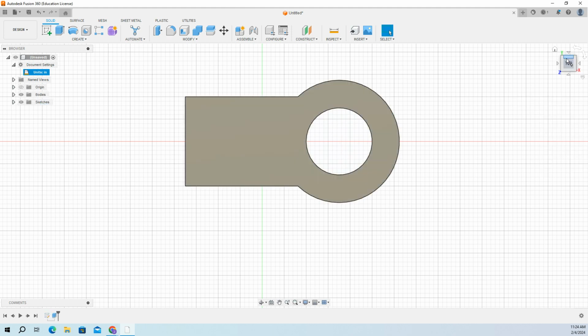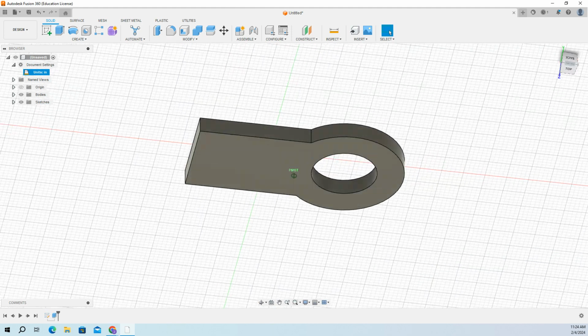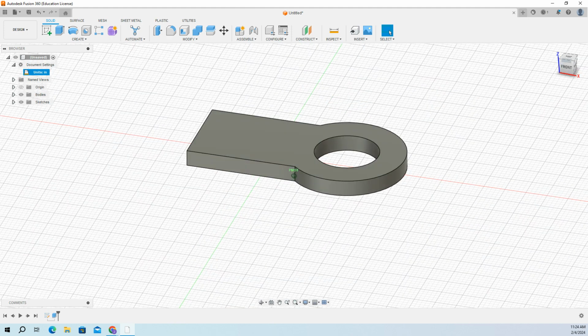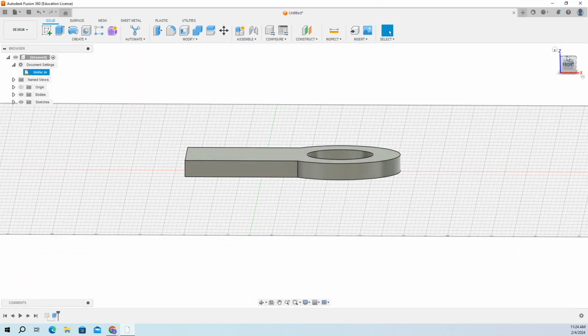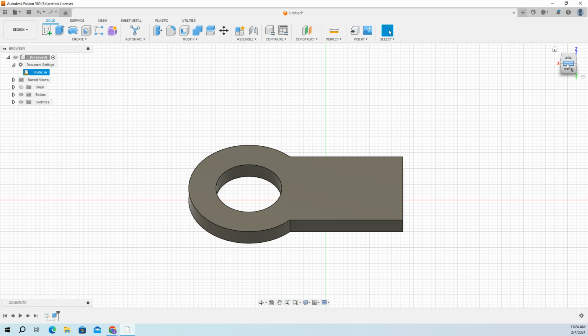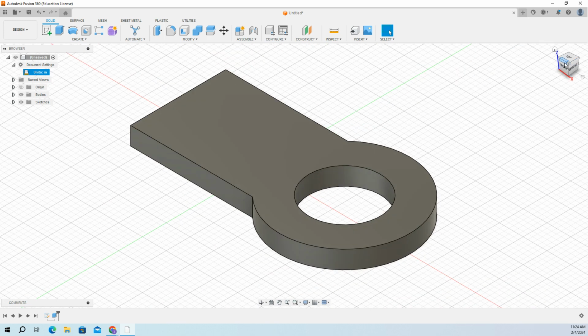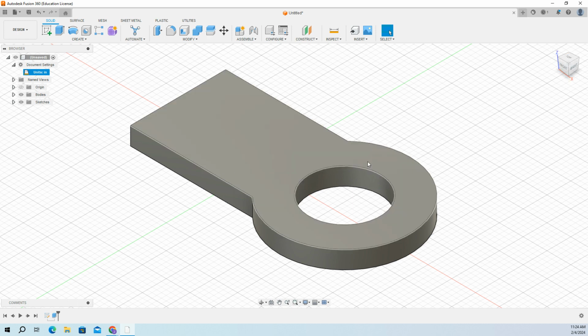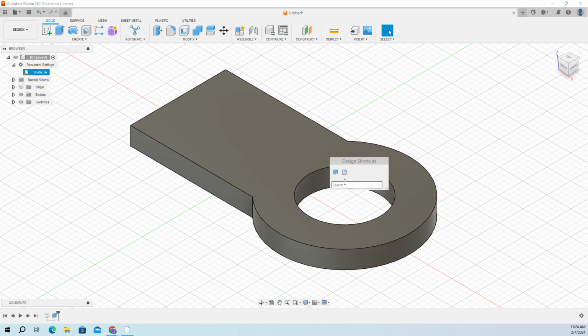I like to just tilt it to know where I'm at, am I doing it right? So I click this angle. Does it look right? If I get stuck, I go back to home, right? So now I have that part. What I was talking about with shortcuts is now that it's in a 3D sketch, right? If I hit S, the stuff doesn't come up anymore for the sketch options. Now you get the 3D, everything's 3D now.